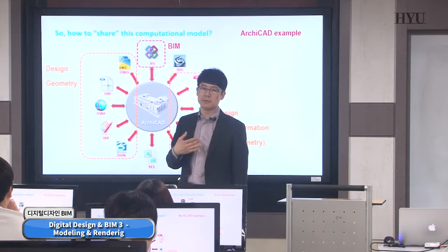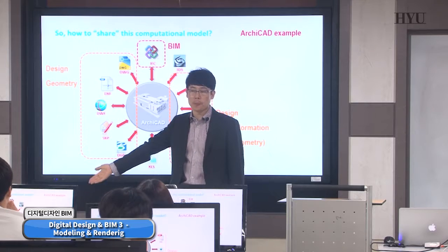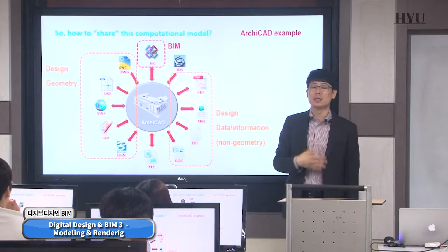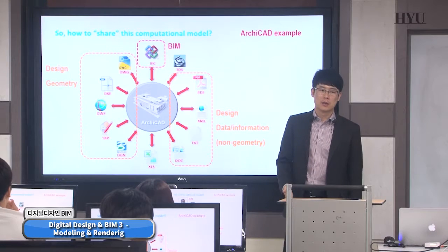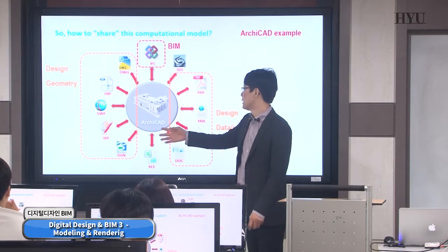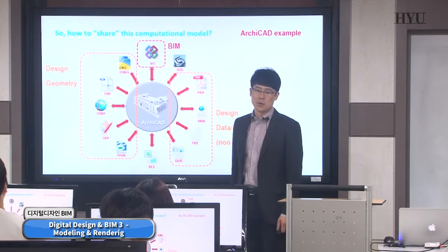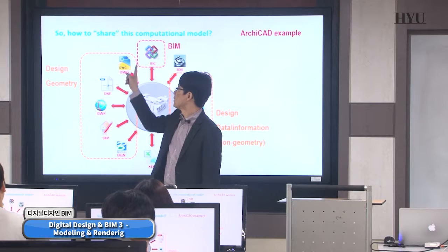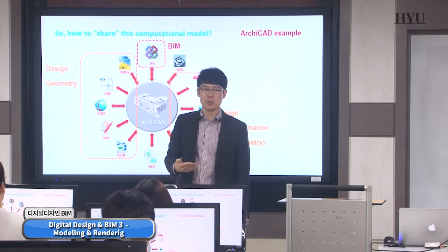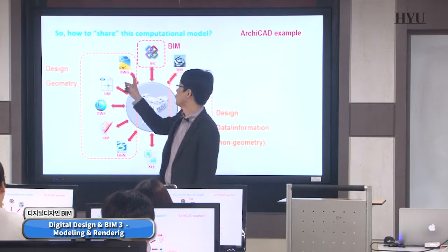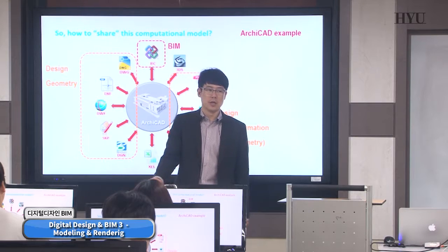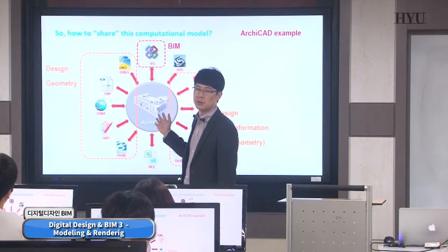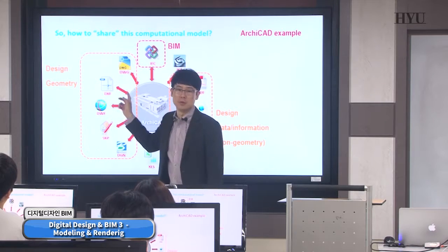So there is no functionality to import or export Revit or others directly. But if you save an IFC file in Revit, and open the IFC file in ArchiCAD, you can keep editing your Revit model, even in ArchiCAD. So simple data exchange or file exchange is like giving your floor plan or your elevation to your teammate. That was your file exchange. But in this BIM area, it is not that simple.